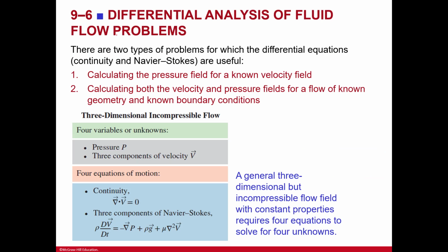So, the differential analysis of fluid flow problems. There are two types of problems for which the differential equations, continuity and Navier-Stokes, are useful. They are calculating the pressure field for a known velocity field, and then calculating both the velocity and pressure fields for a flow of known geometry and known boundary conditions. So that is an unknown pressure field for a known velocity field, and then the unknown velocity and pressure fields for a known geometry and boundary conditions.